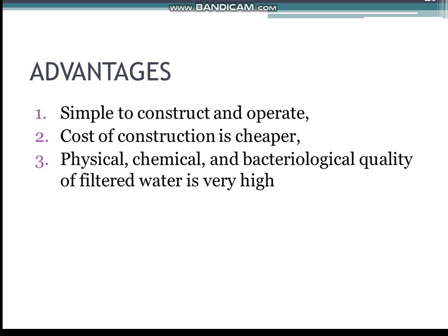After several years of operation and say 20 or 50 scrapings, the thickness of the sand bed will have reduced to about 0.5 to 0.8 meter. Then the plant is closed down and a new bed is constructed.